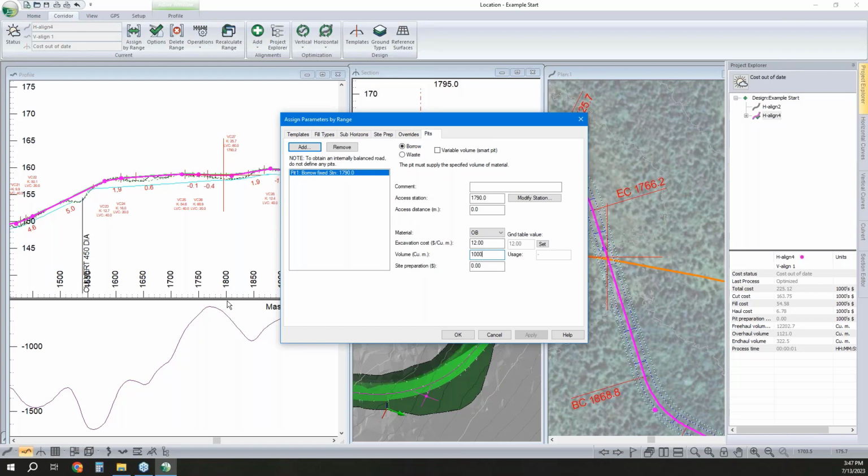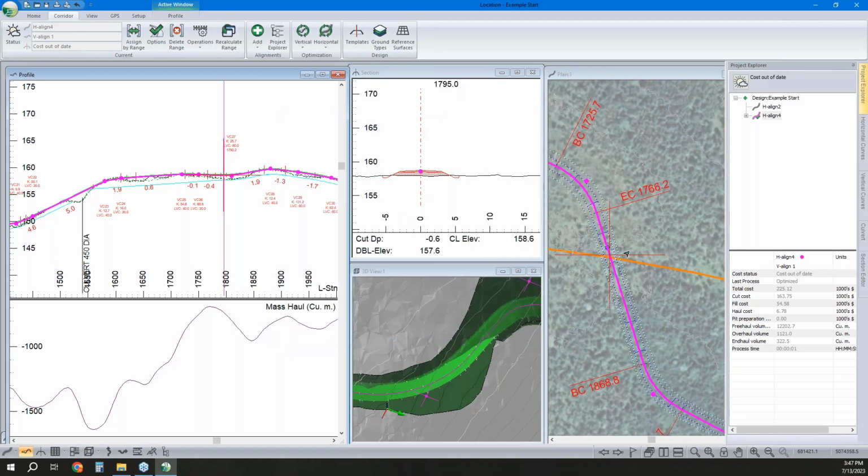Yeah, the practicality of it will depend a little bit on the scale of your offtake ditch. If you're just ditching with a mini, you're probably not hauling that material back there. So if you're worried about costing when you're designing the offtake ditch, you can allow side cast and account for that material just being disposed of adjacent to the ditch.